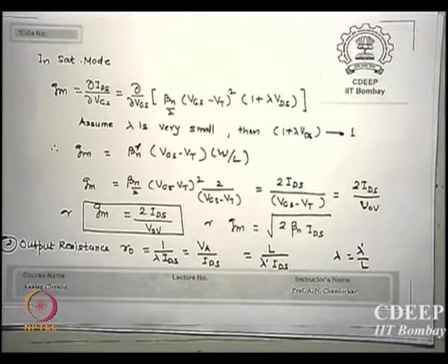Is that correct? So now you have to understand in design, why is it called design? Because if I control R0, I lose track of GM. If I start controlling GM, I start losing track of R0, and that is what people say: I want a gain of this much. Now the designer has to say, I want so much GM and so much R0, how will I get it? That is where the whole design issues arise. In this course, R0 is fixed and GM is known, but I am just trying to give you where the word design comes from. Analysis is shown, and from there we start thinking about what spec I have to meet when I am designing. Is that okay? Yes.